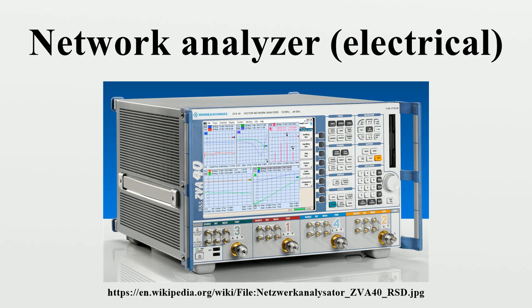The Agilent 85055A kit includes a 10 cm airline, stepped impedance airline, 20 dB and 50 dB attenuators with data on the devices measured by the manufacturer and stored on both a floppy disk and USB flash drive. Older versions of the 85055A have the data stored on tape and floppy disks rather than on USB drives.